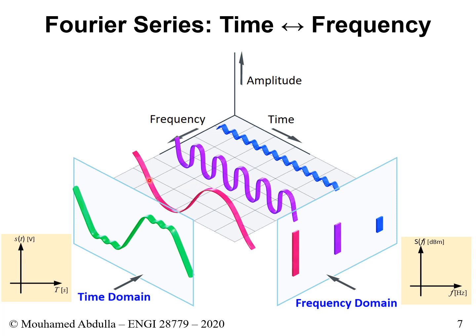Now, in the end, you break this signal down into a bunch of sine waves and cosine waves, right? Sine waves and cosine waves. This is the most basic way of representing a signal. A sine wave and a cosine wave. If you have a sine wave, you get an impulse. If you have a cosine wave, you get an impulse in the frequency domain.